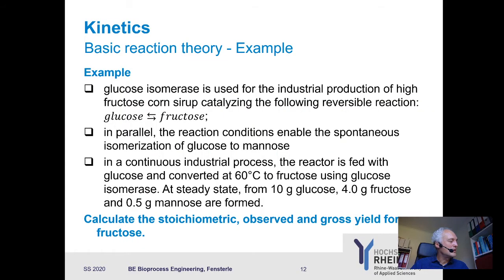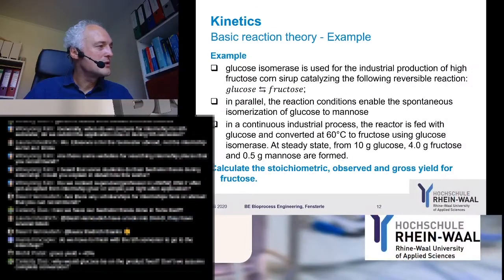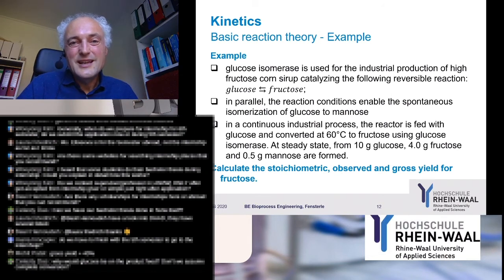Now let's see whether there are remaining questions. Why would glucose be in the product stream? Don't we assume complete conversion? Even if we would assume complete conversion, it's a reversible reaction. You would always assume that only parts of the glucose are isomerized because it's reversible. We didn't put here what the equilibrium is, but if it's 50%, we are already happy here.